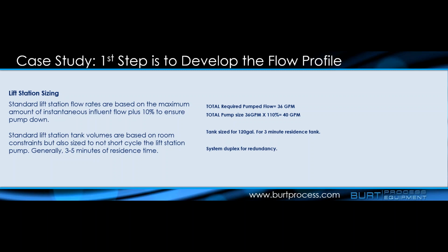And you generally size it for a run time of 3 to 5 minutes. Generally, most pumps you don't want to run more than 12 times an hour. But obviously, there are things that come into play, like how much room you have for the system. Most lift stations, they try to make the tanks as small as possible for real estate purposes as well.